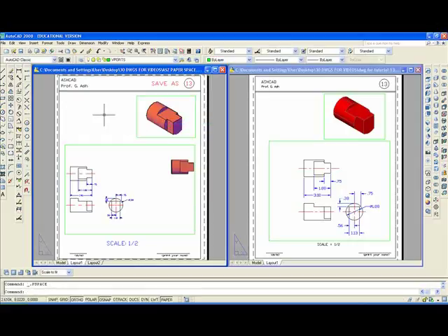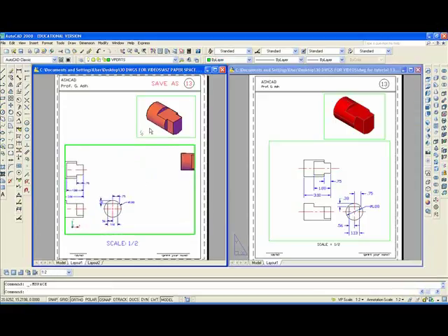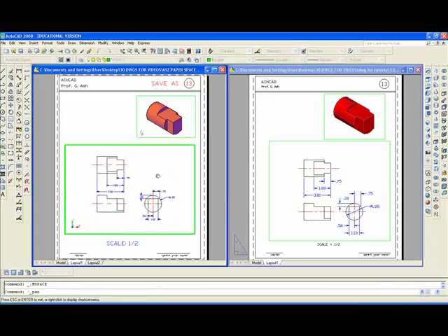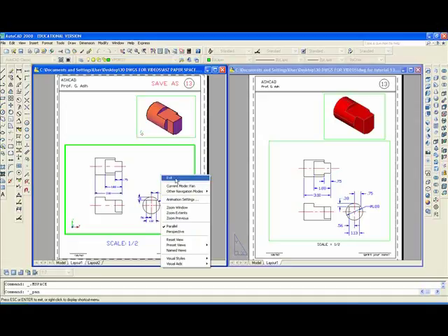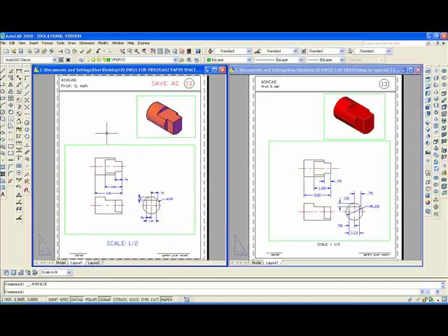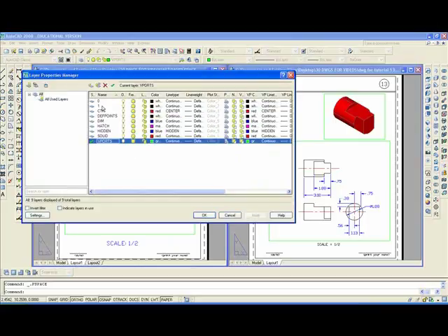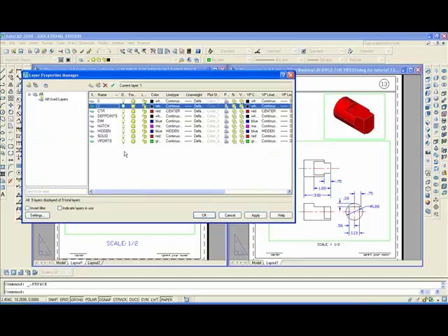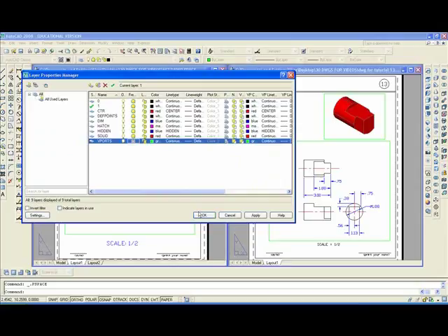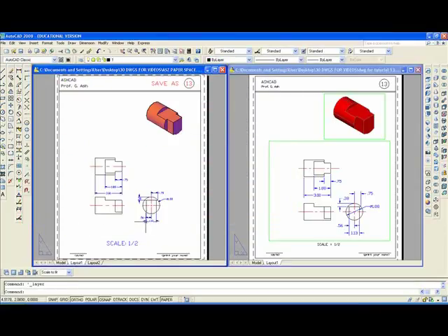Double click outside, click on the 2D drawing frame, and then go to annotation scale. I guess it's got to be a half. Got a little bigger. Double click inside, then just pan to locate it properly. Then if you want, you can go to layer and you can make layer 1 current with viewports freeze. The reason the dimensions are smaller is because I forgot to change the dim scale.